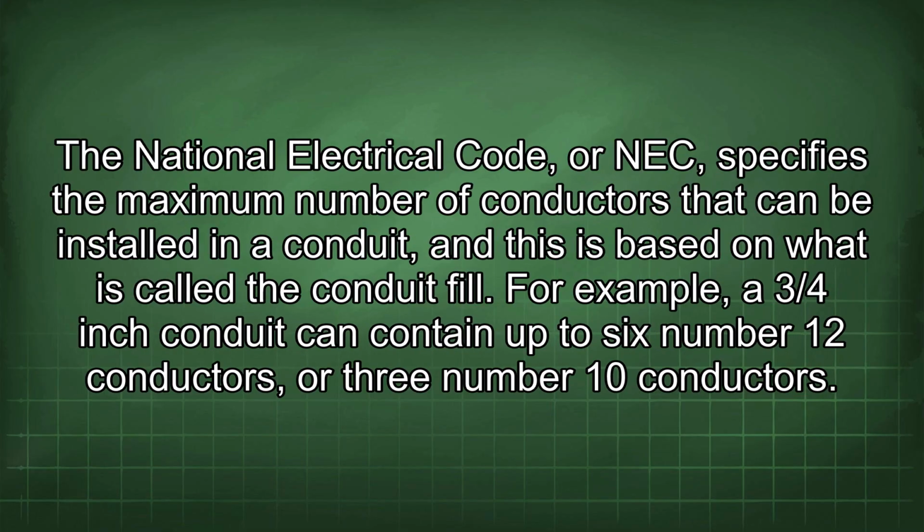The National Electrical Code, or NEC, specifies the maximum number of conductors that can be installed in a conduit, and this is based on what is called the conduit fill. For example, a 3/4-inch conduit can contain up to 6 number 12 conductors or 3 number 10 conductors.